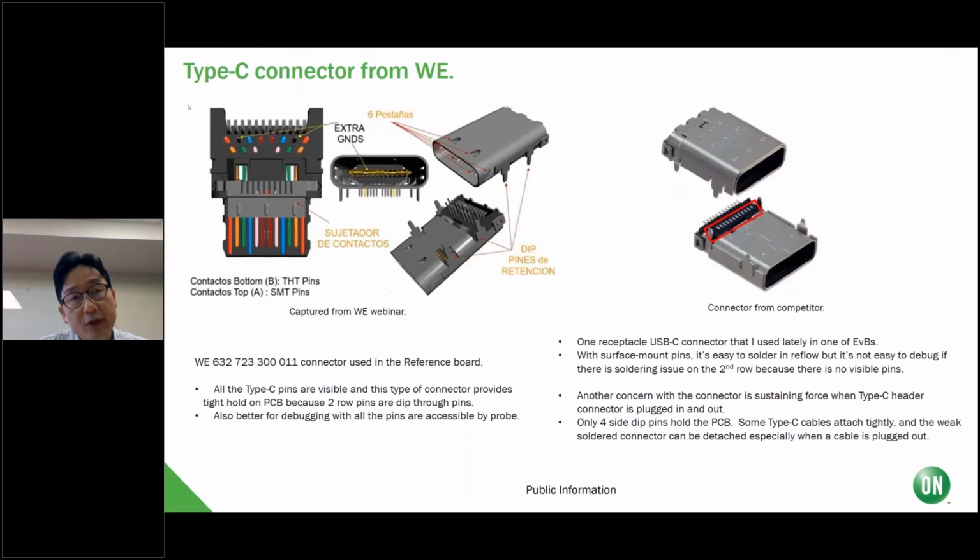I've actually been using it in another EVB lately, and I had some issues with this connector because in the reflow station, the solder cream was not much on the second row. So only the CC1 is on the outside, and CC2 is on the second row. So one CC line was not working in my evaluation kit.